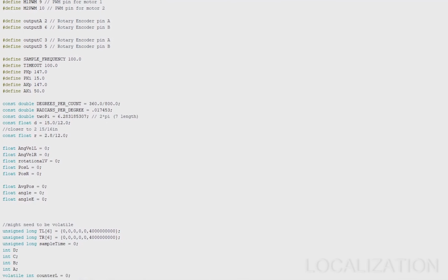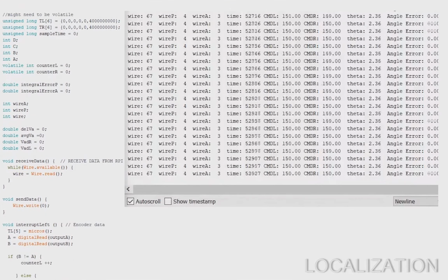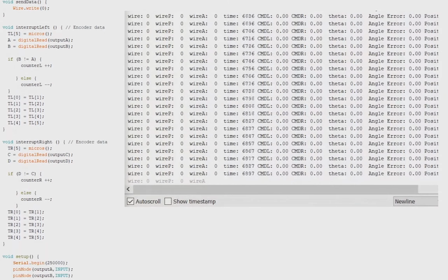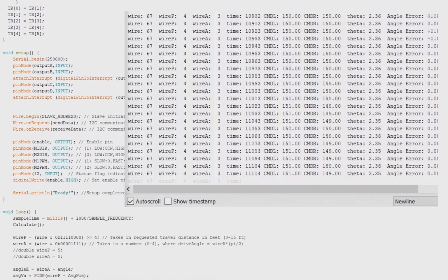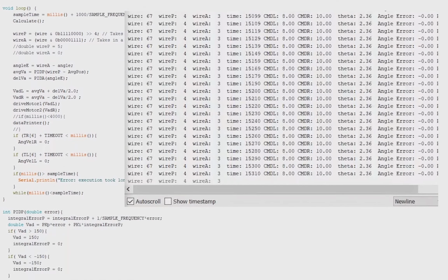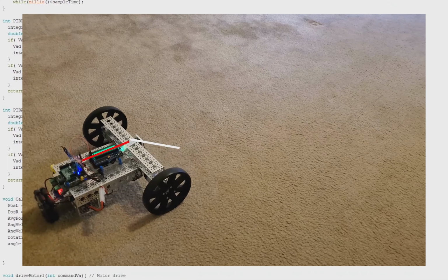The localization subsystem of the project involves programming the Arduino to read data from the rotary encoders present on the motors and writing drive values to those motors. The Arduino uses two interrupt service routines along with rotary encoders to constantly track the amount of turns each wheel makes. This data is used to calculate the Cartesian position and angle the robot is in.